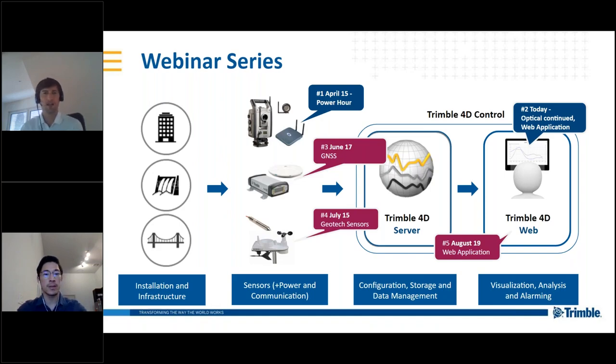Eric Hayes was actually chatting me while this is all going on. He moved the target a little bit too far, and so the total station had a little bit of trouble measuring it. Okay, he's making me the presenter now. We got another round to go through, and we can see it on the web. I think the reason was that if you move the target a little bit too far, considering we have really short distances, in this living room about 3 meters, then moving a target by just 1 or 2 centimeters might lead to a situation where the target cannot be found anymore by the total station. But this is a different story. I guess you understand how to create an alarm, and I think that's fine for now.